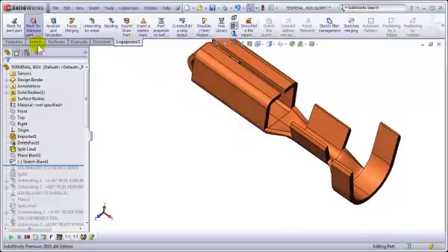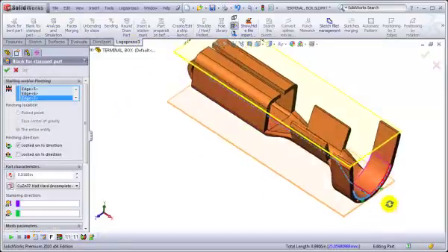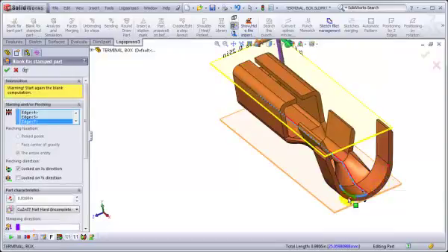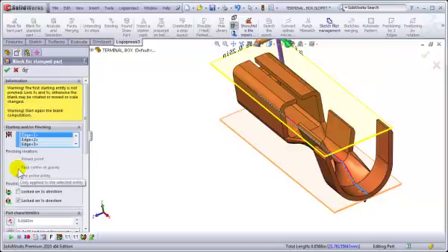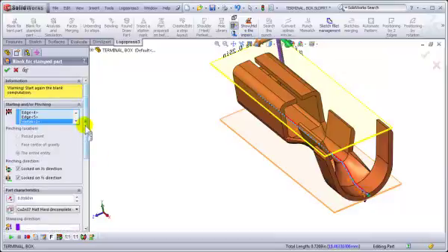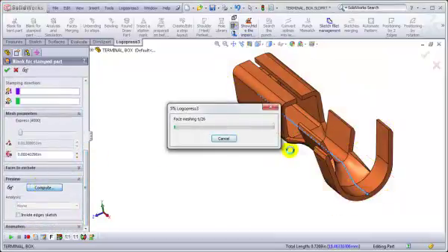And then we're going to go back into Logopress3 blank for stamped part, and we'll deselect these two edges. That's what made it straight before. And then edge number 1, we'll unlock that in the X direction. And then we'll also pick this point and we'll lock that up in the X and Y direction. And then we'll compute. And that will allow that leg to move as it will move in real life.